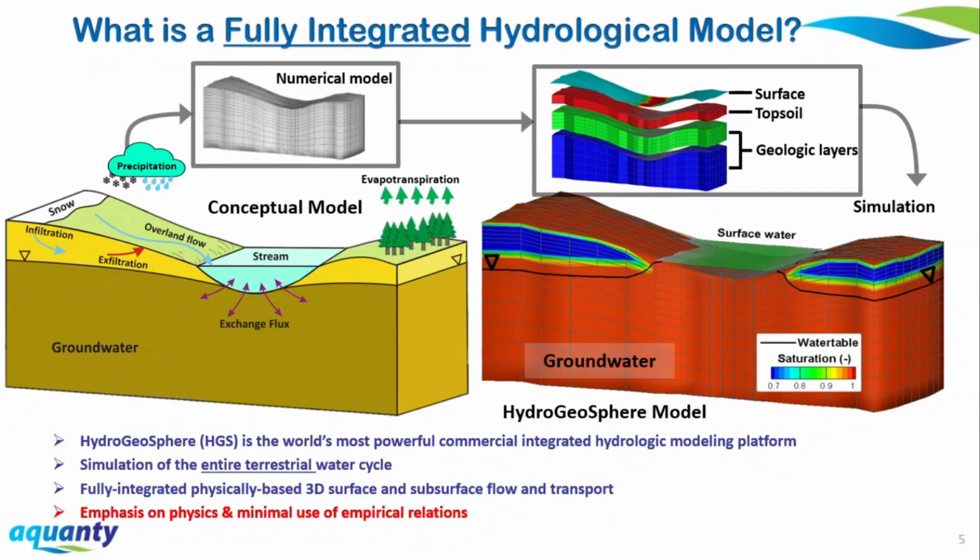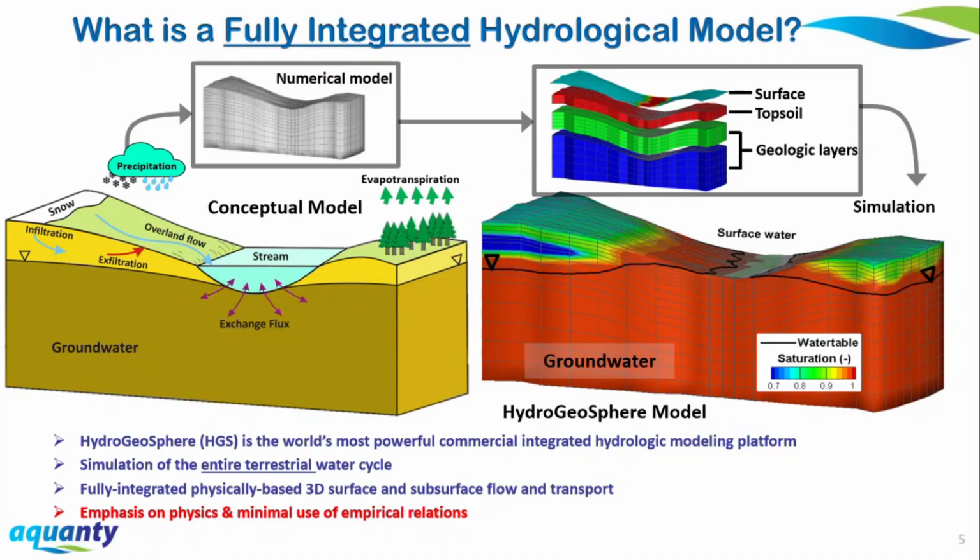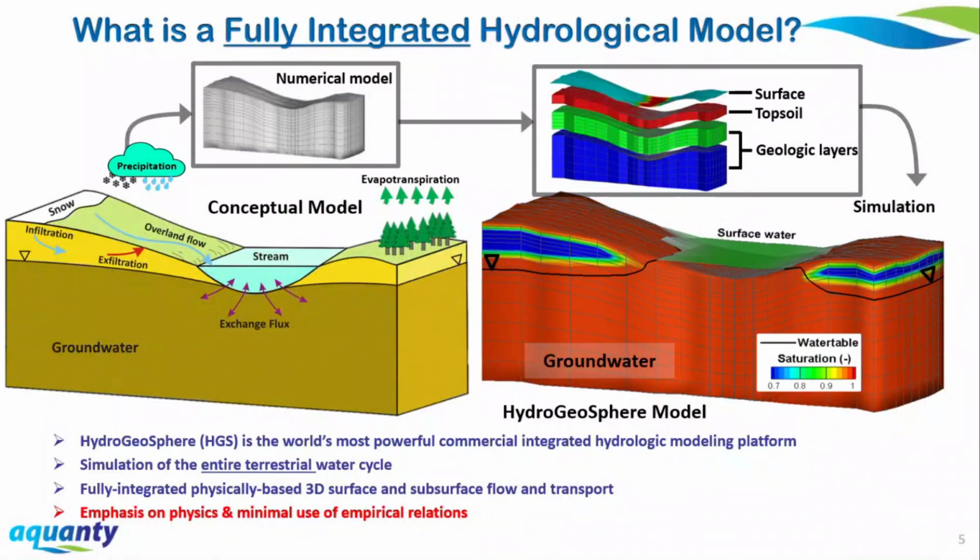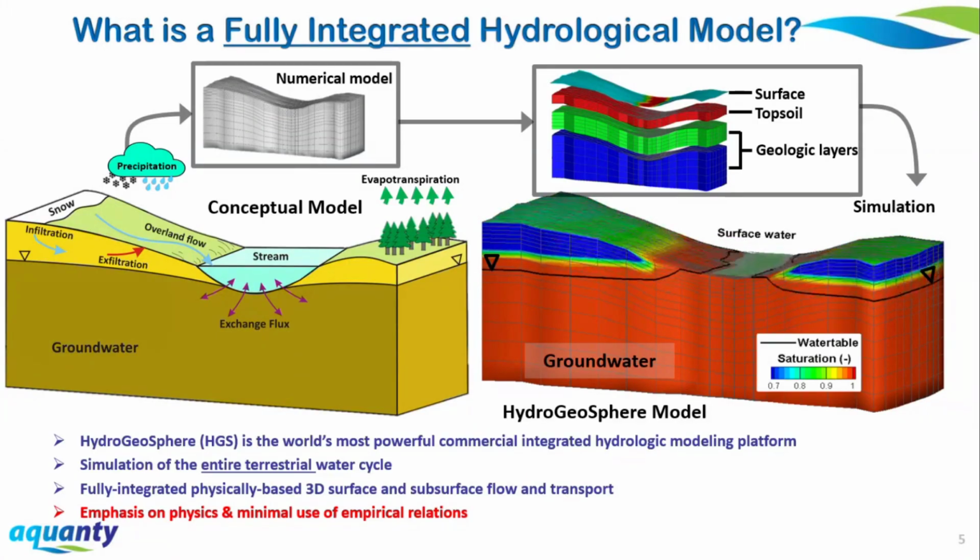Depending on the state of the system, excess water can either infiltrate into the ground or run off. This can have a direct impact on things like soil water storage, water table position, and surface water-groundwater exchange in both directions. It's nicely illustrated with the animation on the right, where we see infiltrating water, the resultant rise in the water table, and rise in surface water. So the basic takeaway is that the effects of rainfall on both groundwater and surface water are included simultaneously.